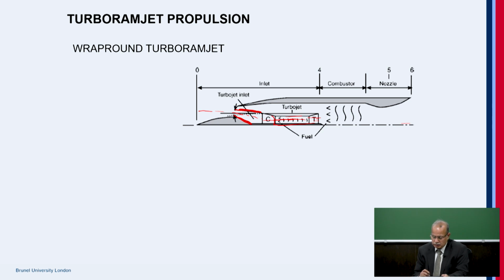Now when you have reached the required ramming Mach number, maybe 2.5 or something, that range, then the flaps can close the entry. Before it closes, it can go to the dual mode of operation, where the air partially gets into the engine and also gets into the ramjet. Then it closes and full 100% operation with the ramjet, where the air enters in through the inlet, and then you can see such a long inlet.